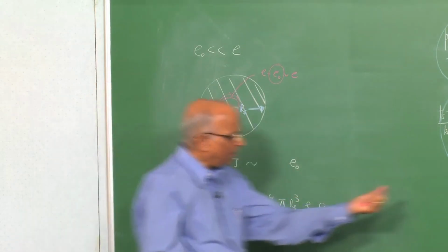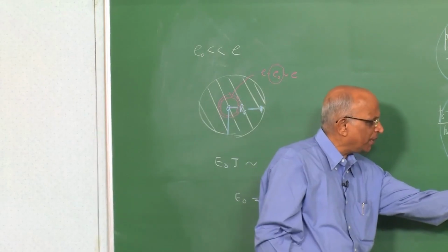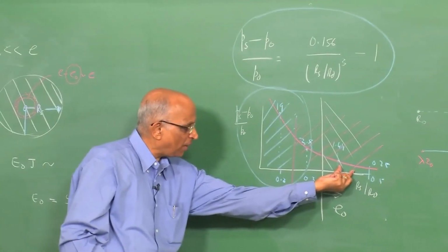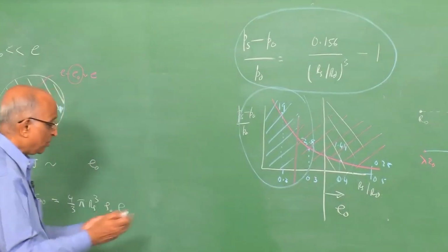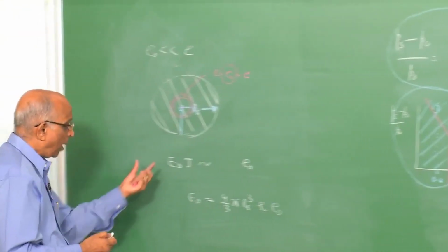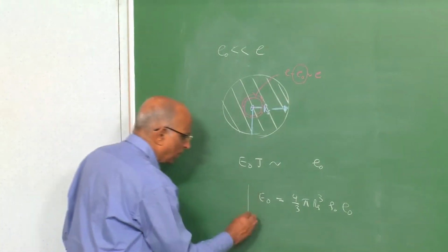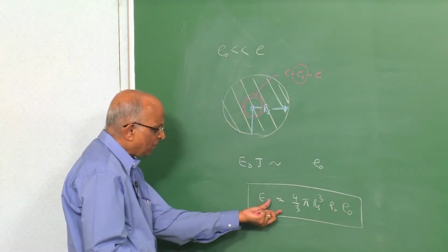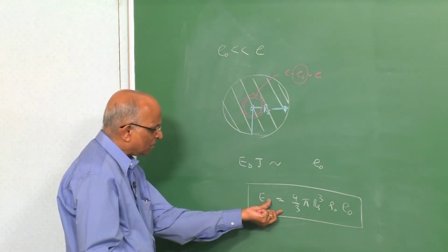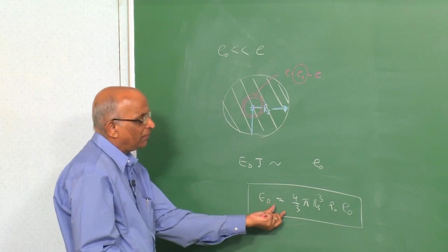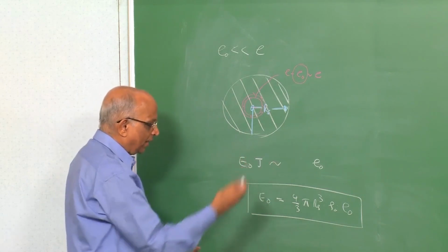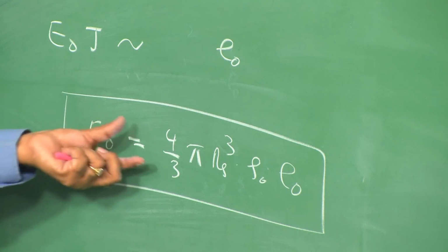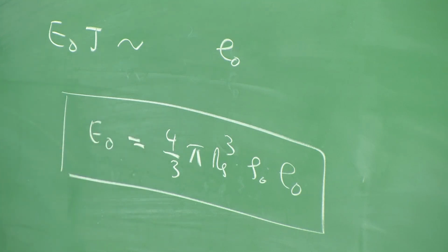Well, I should be able to get this particular point, and beyond this what is happening is the initial internal energy affects my shock, or affects my overpressure, affects my Mach number of the shock, and therefore, I can look at this particular expression and get a feel for what is the value of Rs by R naught from this expression, which will decide the region in which my predictions are quite reasonable.